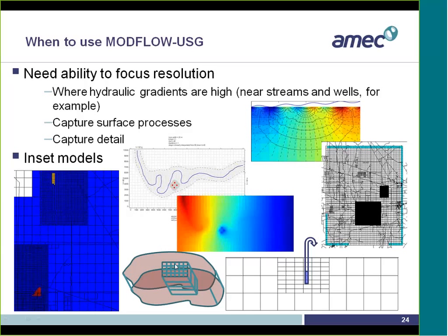You may have local scale evaluations with multiple layers for mining or such applications, and the regional impacts may be modeled without having this fine grid going out to the large scale regional model, as well as without having the multiple layers if you do not have much information about geology to make such multiple layers. Just these finer discretizations may be just for the mine workings themselves.